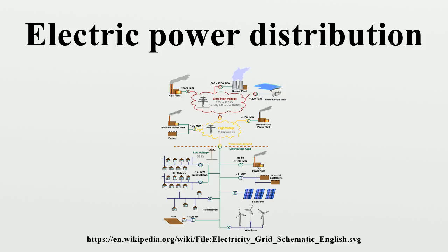The exact voltage level depends on the amount of power to be transmitted and the distance. Different standardized voltages are used in different countries, depending on local engineering practice. Power is carried through this transmission network of high-voltage lines for up to hundreds of kilometers. For reliability and economy, transmission systems are interconnected to form the electric grid, which may have many sources and loads interconnected. Sometimes intermediate, sub-transmission voltage levels are used for smaller loads or geographically isolated places.